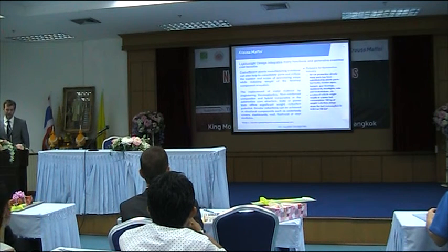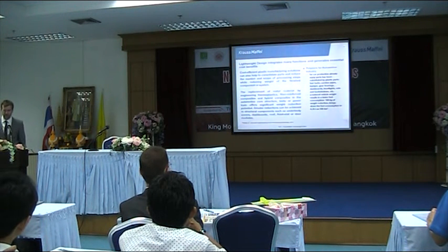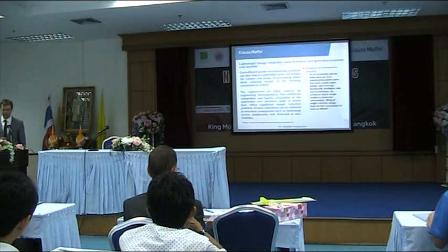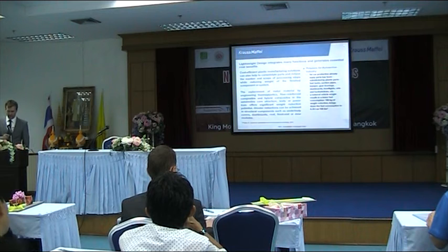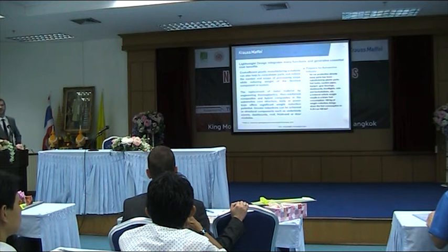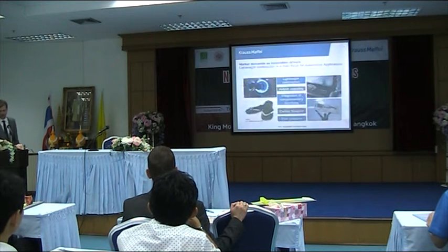Now I think this is one of the main goals: the replacement of metal material by engineering thermoplastics and also fiber reinforced composites and hybrid composites in the automotive core structure, body or powertrain offers significant weight reduction potential. The greatest reductions can be achieved in structural components, for example underbody covers, dashboard, roof, front end, or door modules. And now fibers get important. This is the main goal, to reduce weight, and we can achieve it by using fibers.